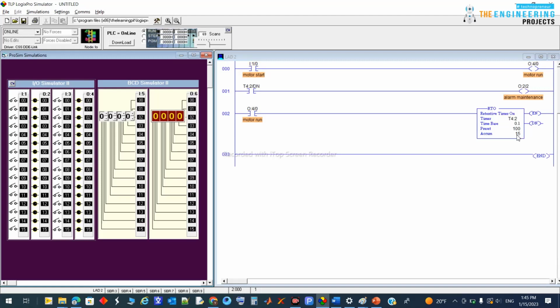So I count here like 15. Once I don't have this input, the accumulator still retains the value of 15, and the machine worked for 15 units of time, and then it counts again, reaching 40 units of time, every single time I run the machine. Okay, so you can see the counter, and at the end of the day I stop the machine and go back home.